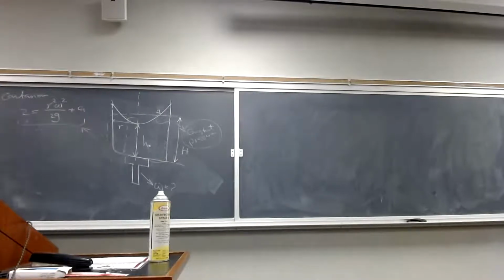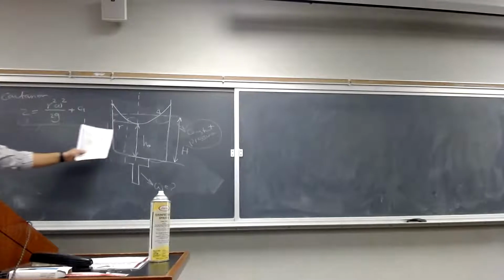Have you passed any of your lab courses? Yes? Okay, if you have passed your lab courses, and if you have had a bending experiment, we have these measurement devices. If you bend the system, this will move with the bent rod, and you can measure this distance, this deflection. It's essentially the same idea. I don't know if you have done any bending tests, but the point is, it is easy to measure this height.